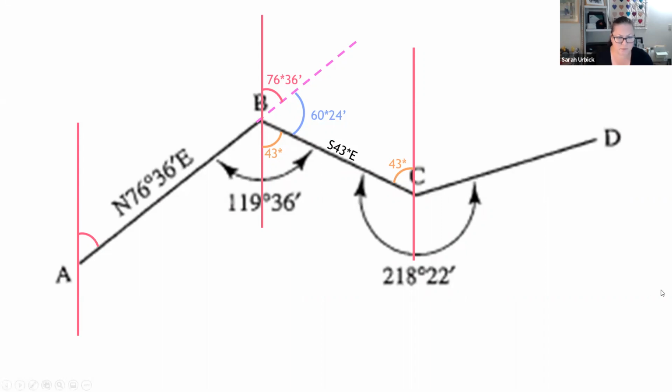Start by assuming we will measure the bearing for CD from the north meridian. Okay, so this is what I'm getting at here. From our north meridian, what's our angle coming back to D, to CD? All right, so let's assume that we're going to be in that northeast quadrant.